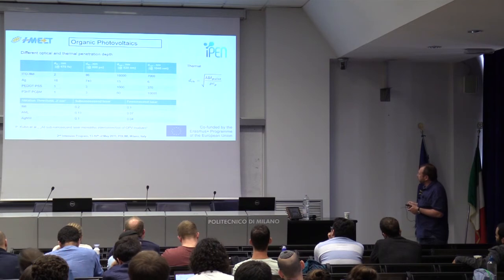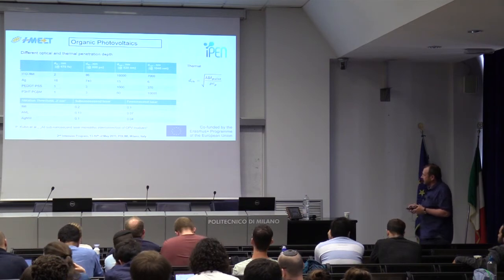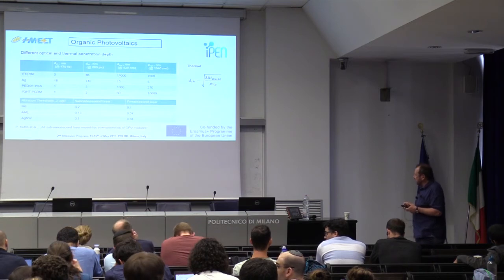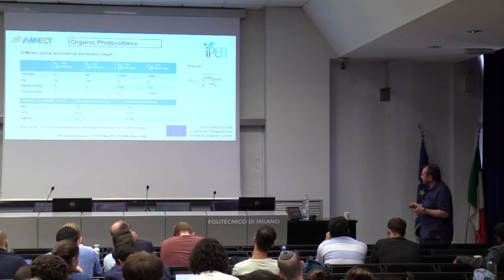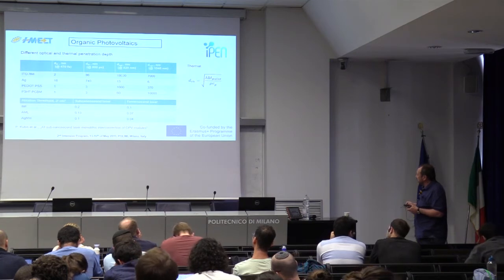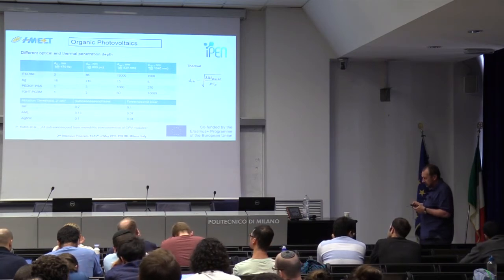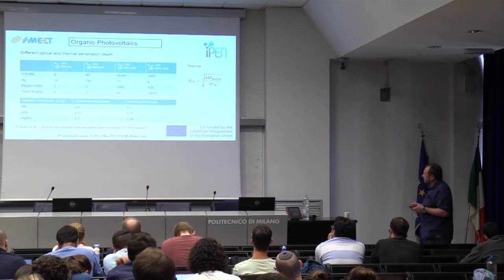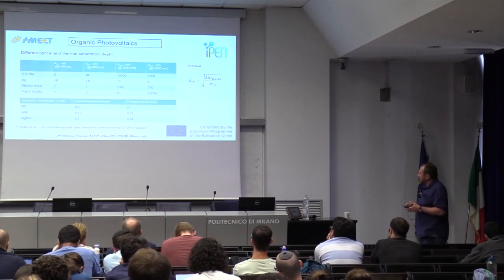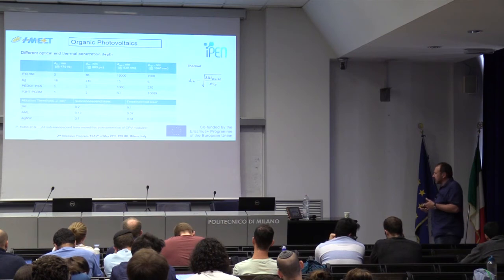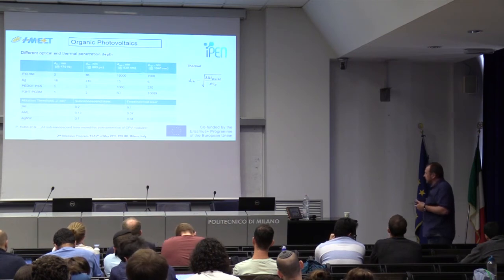So, as you see, the transparent electrode material does not absorb the laser light very well. Absorbance is a little bit higher at 520 and not higher at 1040. This is because of the free electron absorption here. On the other hand, the thermal conductivity is not so good, and the thermal penetration depth is relatively low, and the effective or general penetration depth is determined by these values here.